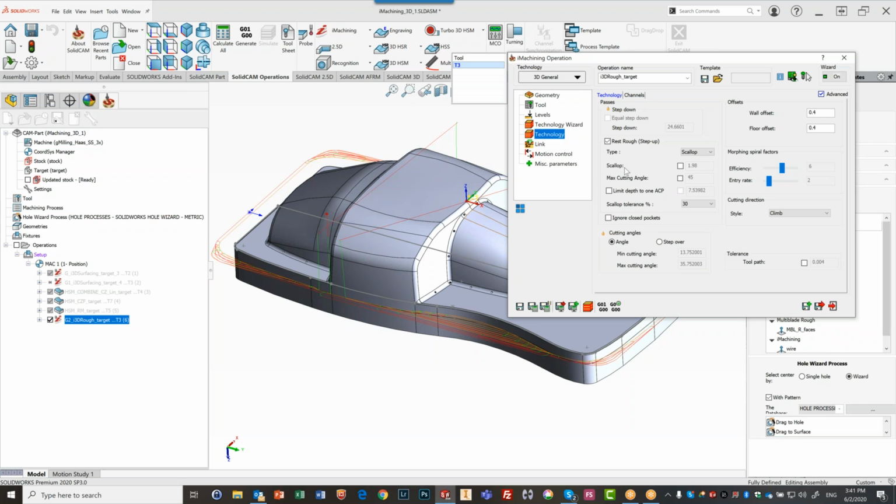You'll note we control it by what we call a scallop. Okay? If you take a look at the picture at the side over here, we say how big of a scallop do we want? And it'll automatically give you the proper scallop according to the actual angle of the material. At a steeper area, the scallop will be bigger. Shallower areas, there will be more scallops. Okay?